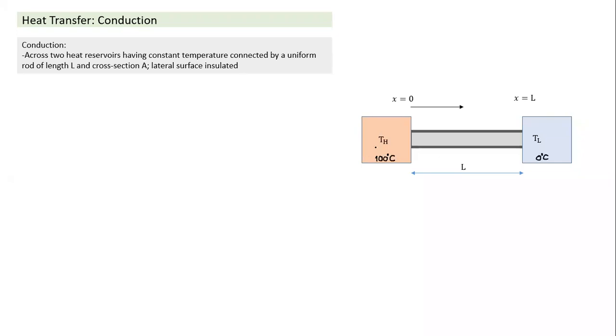So how do we maintain constant temperature? If in a chamber we have steam at 100 degrees centigrade, it will act as a constant temperature reservoir, because even if I take away some heat from here, initially the temperature will not change. When you take away heat, some part of the steam will condense, but it will become a mix of water and steam at 100 degrees centigrade.